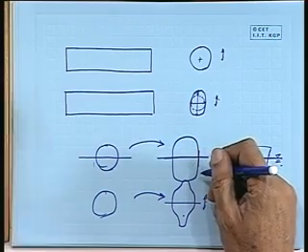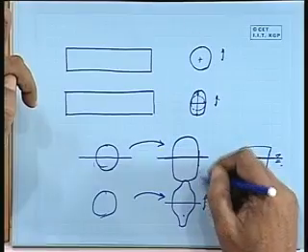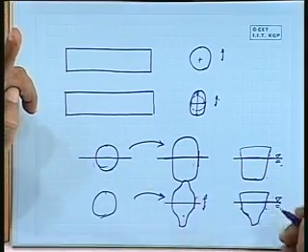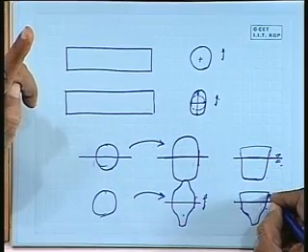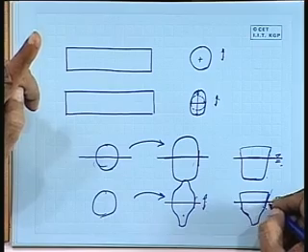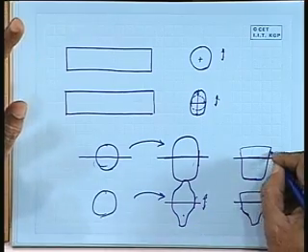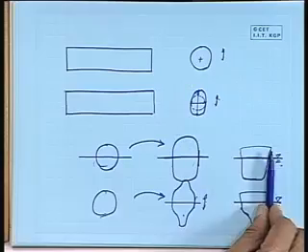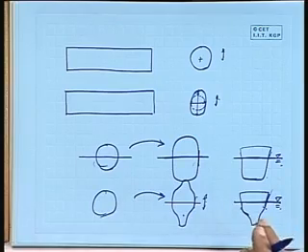The tangent is perpendicular to this line of symmetry. But when you try to draw a tangent here, it is not perpendicular to the water surface, because you have flare, and when the ship vibrates, the shape is something like that. So, it is not perpendicular here. So, that will require certain corrections.